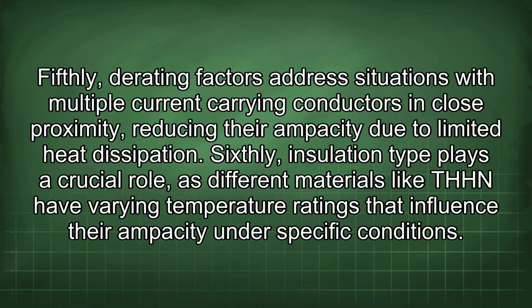Fifthly, derating factors address situations with multiple current-carrying conductors in close proximity, reducing their ampacity due to limited heat dissipation. Sixthly, insulation type plays a crucial role, as different materials like THHN have varying temperature ratings that influence their ampacity under specific conditions.